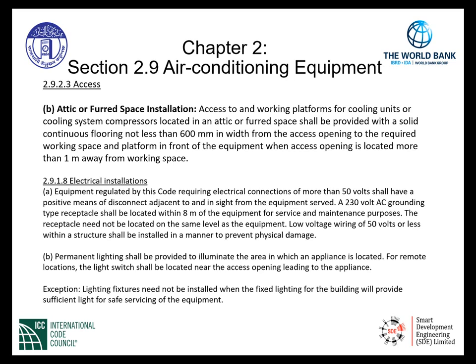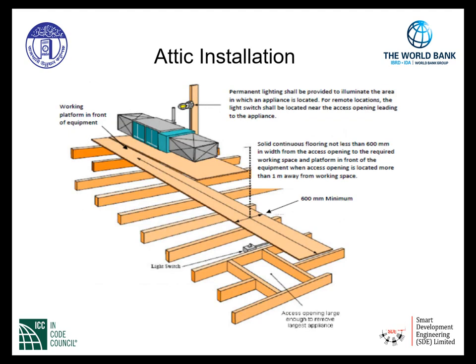Not only do we have to have safe access, enough access for servicing the appliance, but we also have to have a receptacle and a lighting fixture at the location of the appliance for the service personnel accordingly. An attic installation is given below.